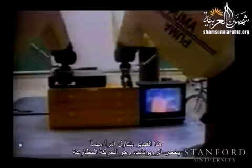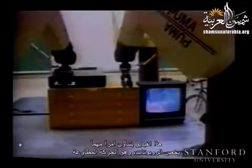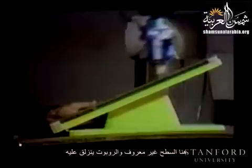So this video is about a very important aspect of robotics, which is compliant motion. You see the sponge is pushing up, and you see no deflection on the sponge, which means that there is no force applied. Here we are coming to a surface that is unknown, and the robot is sliding over the surface. So it's making contact at different points. Even if we remove the whole object, now here is a wavy surface that is being followed just by saying press down and move to the right, cleaning a window without breaking it.